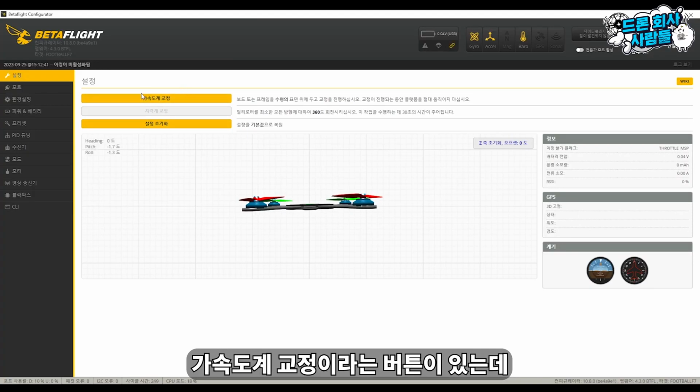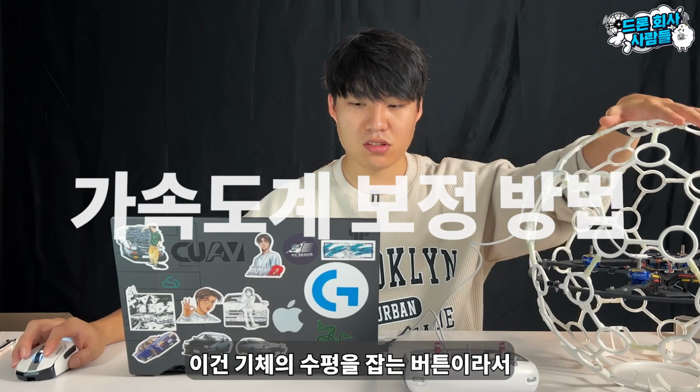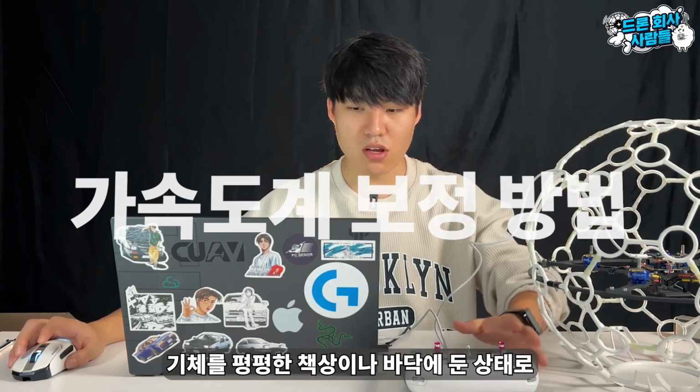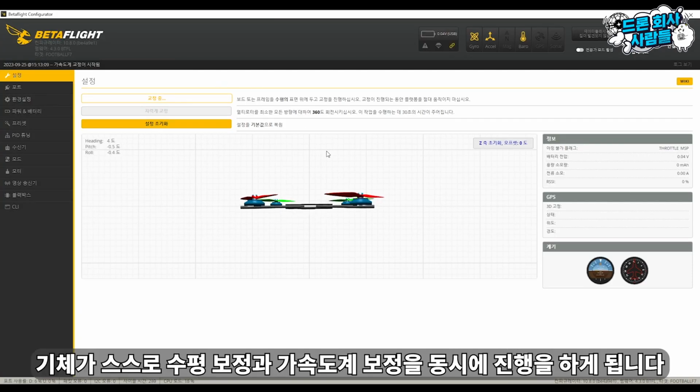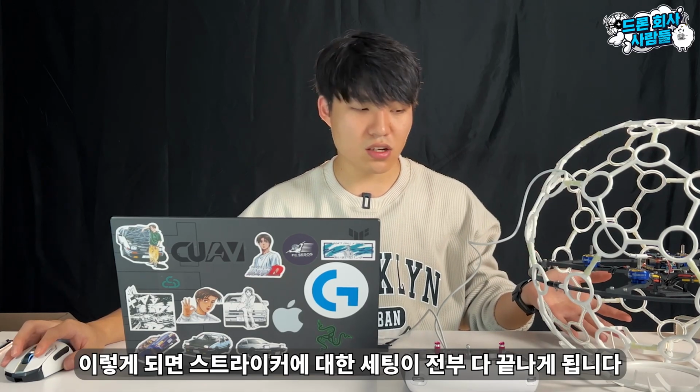is a button for accelerometer calibration. This button is for leveling the aircraft, so place it on a flat surface like a desk or the floor and press the accelerometer calibration button. The aircraft will then automatically perform level and accelerometer calibration simultaneously. With this, all the settings for the Striker are complete.